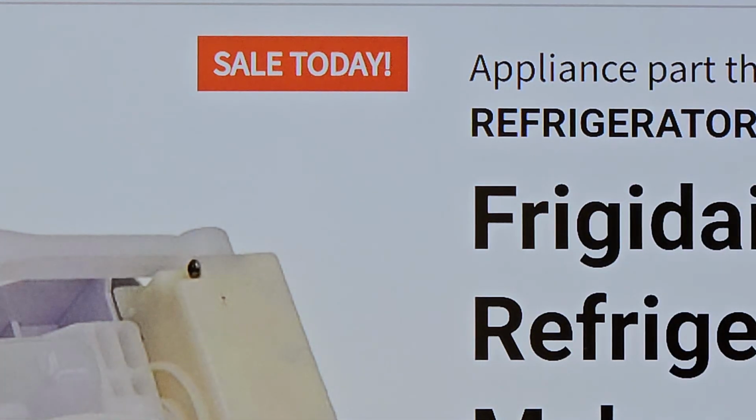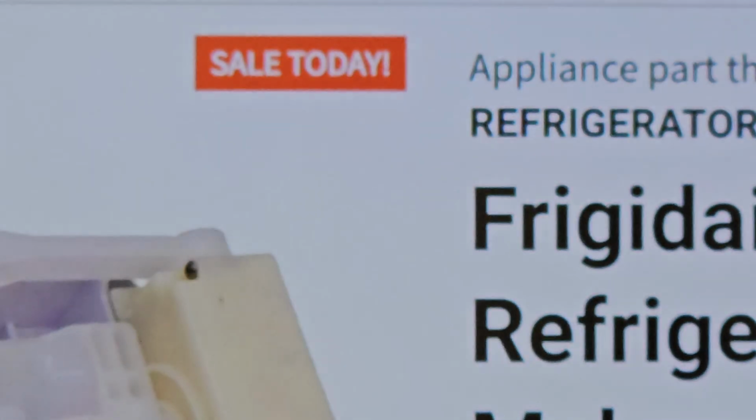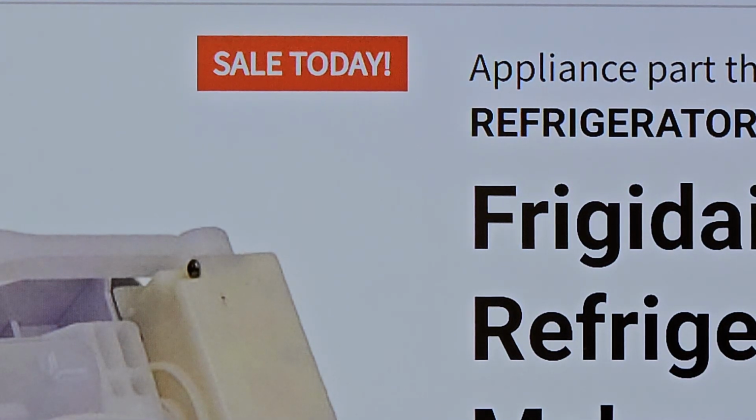But again, troubleshooting these things out, you have to understand how they operate. And you have to know there's no control board in there. These wires here are plugged to the main board and the main board's telling it what to do. And if the diagnostic is working, that means the board itself is working. If the diagnostic is telling the motor to drop the ice, there's nothing wrong with the circuitry to the motor to drop the ice in the first place. So the only thing wrong is it's not telling the board to drop the ice. When you go to diagnostics, you tell the board to drop the ice, but it's not doing it on its own.